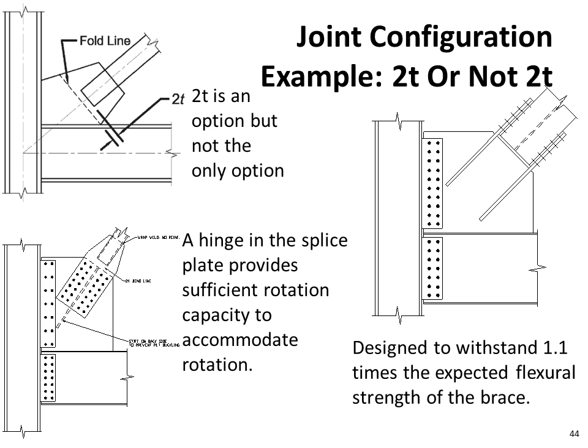So right below that, there's a detail with a hinge plate, where rather than having the out-of-plane motion being accommodated in the gusset itself, it's handled in that splice plate. It's very similar detail, but a little bit different configuration.